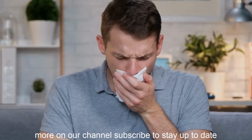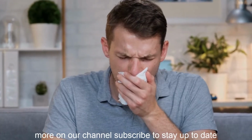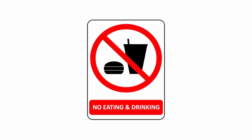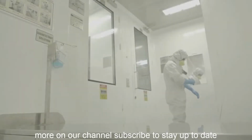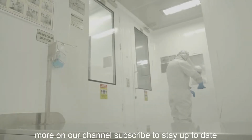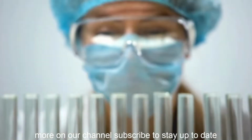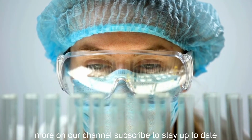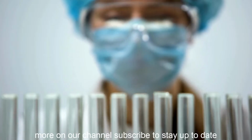Personnel with health conditions that could compromise product quality, e.g., open sores, respiratory infections, should be restricted from working in relevant areas. Eating, drinking, smoking, and chewing gum should be restricted to designated areas outside of manufacturing zones. For instance, before entering a clean room for sterile manufacturing, personnel follow a stringent gowning procedure, putting on multiple layers of sterile garments to minimize shedding of particles and microorganisms from their bodies. Maintaining a high standard of personal cleanliness and following hygiene procedures is a personal responsibility for every employee and a vital part of preventing contamination of drug products.